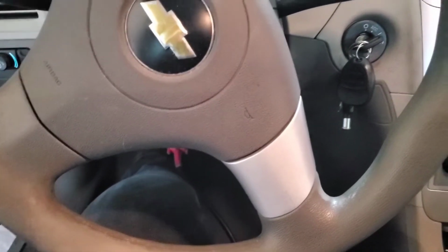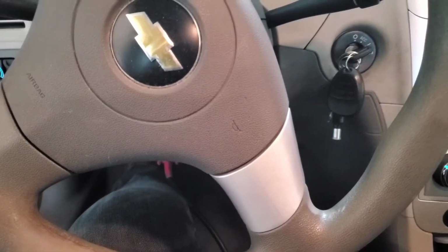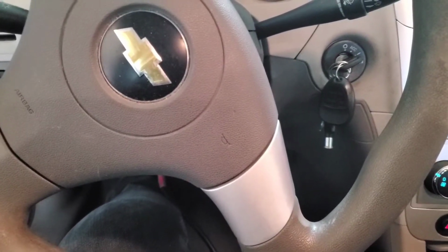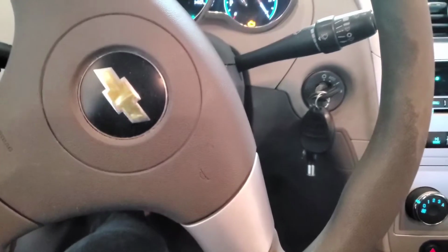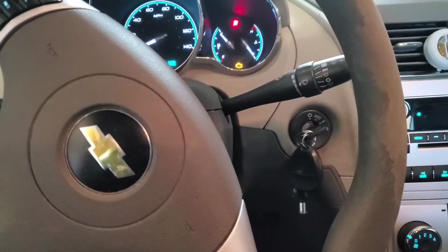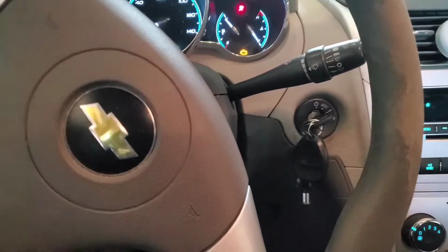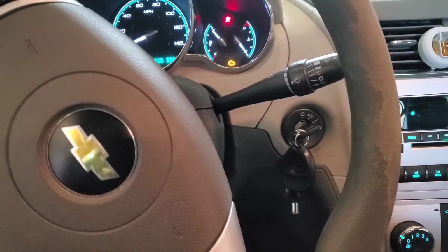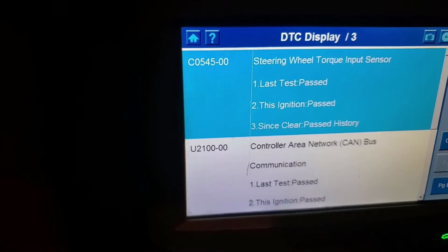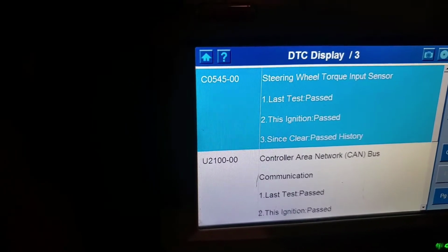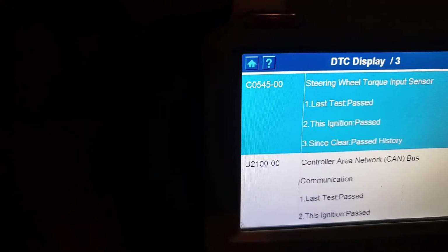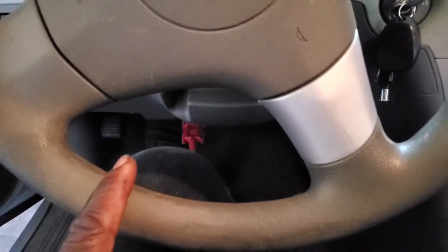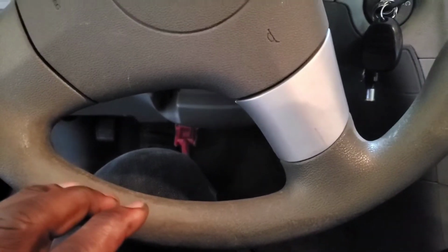We could do that. I could put a scope on the signal wires and just watch what kind of bus signal I have. I won't be able to interpret it, but I can see if I have good comms when I have that failure, see if the bus goes away. It might just be a timeout signal when the brake control module goes offline and whatever failure is causing the power steering control module to suspend operation. So I'm going to check the integrity of the bus, see its resistance, and make sure of the terminating resistance.